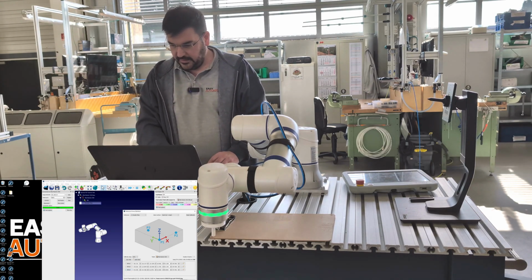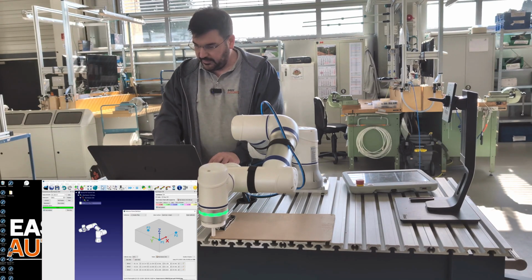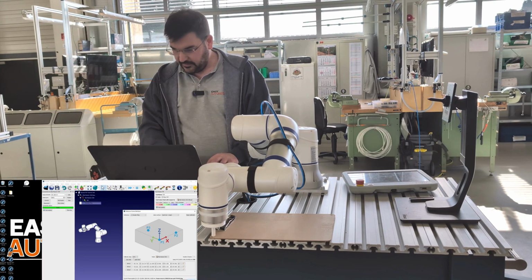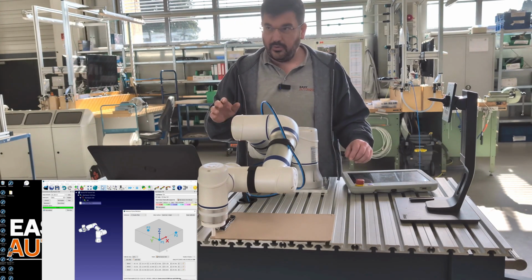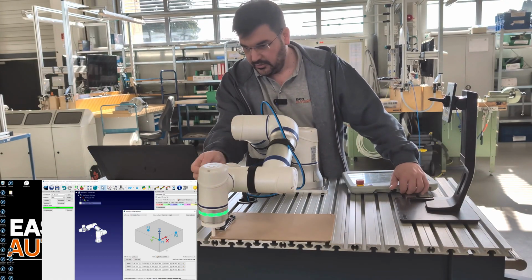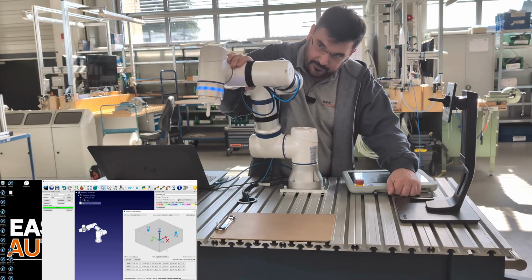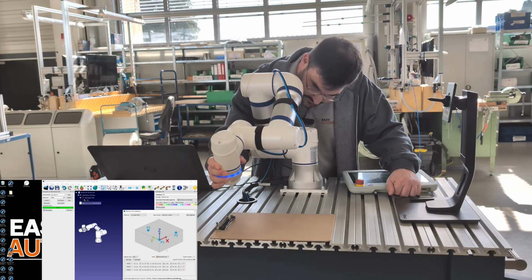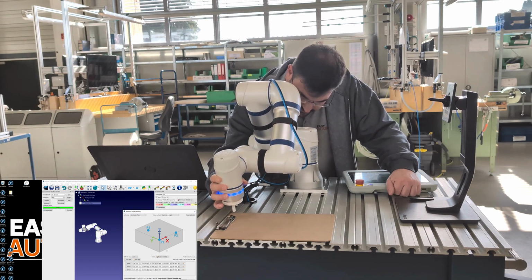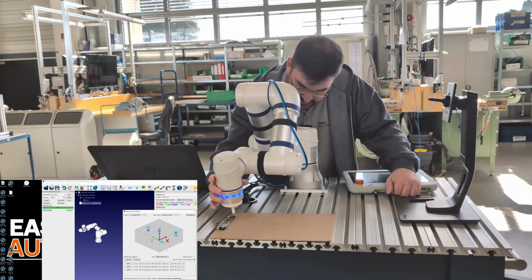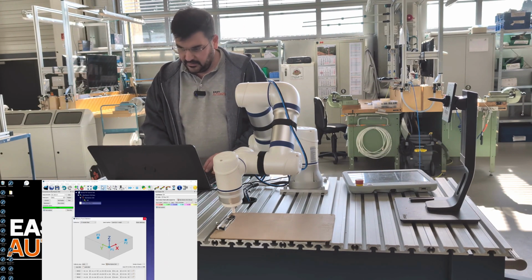So you can see the frame error is 1.358 millimeters. I just update this. This is good enough for me. And before we go to the next step, I always recommend you do this. You just simply come back to the 0 position, or approximately to the 0 position, to test if the 0, the origin, is really the origin. So here you have the chance, without any additional pain, to see if we are approximately in the right position.